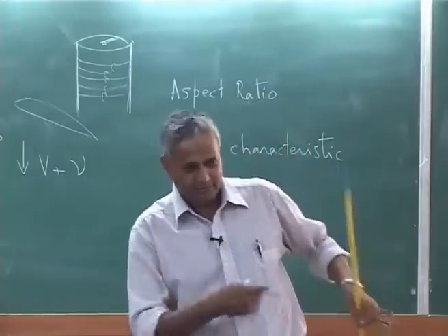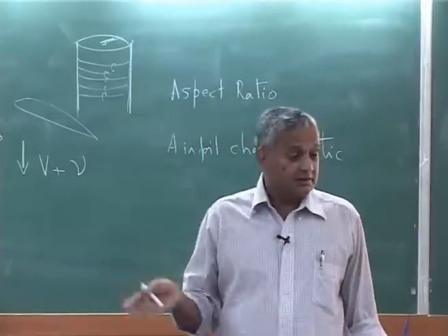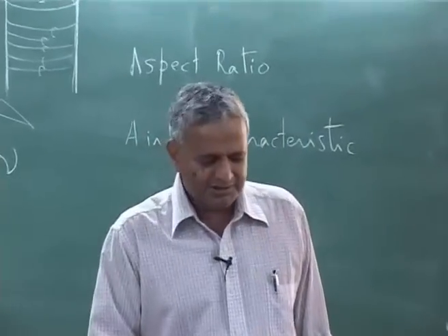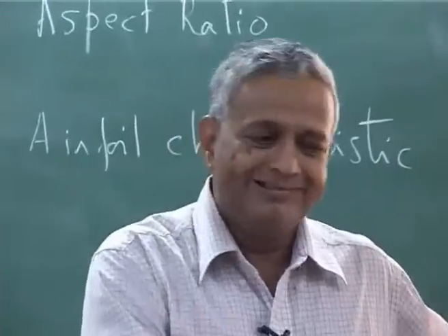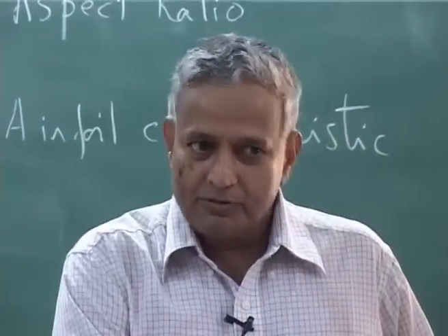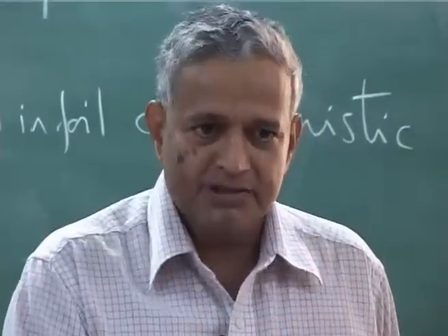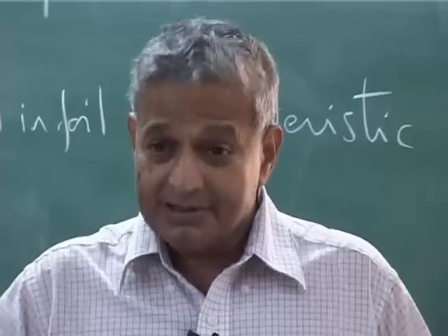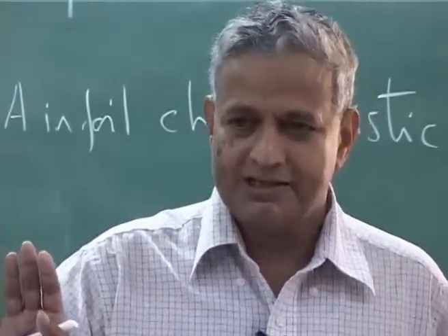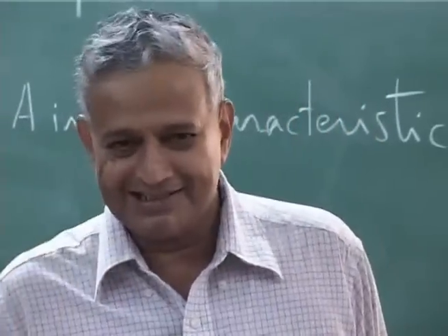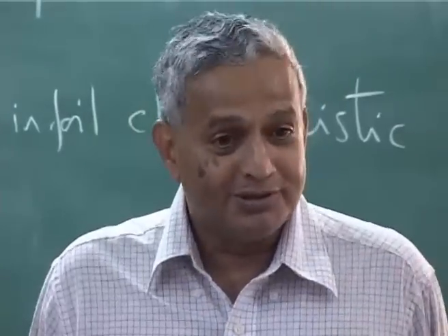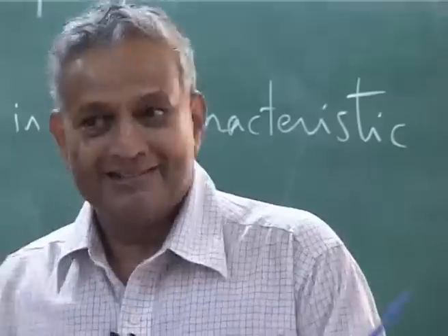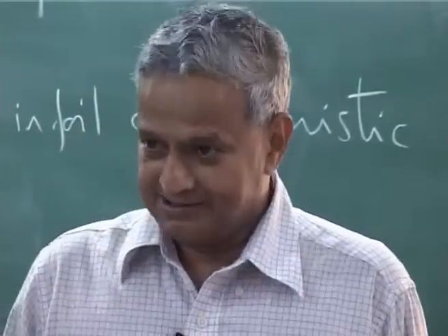I will show you later how we use it, because if you want to have vortex theory, then you need to sit and develop it. It is computationally more intensive, whereas you will find even with momentum theory, the results which you predict are reasonably good, pretty good I would say, but you have to make some corrections here and there. With that your results will be good, and that is why momentum theory is still used in rotor analysis.